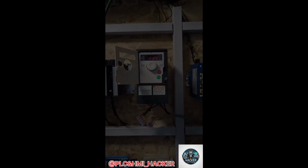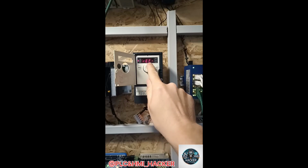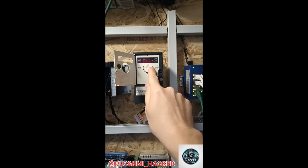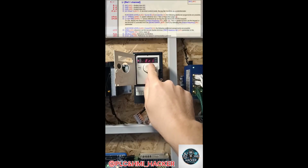We need to change where the drive should be controlled from. If we go to the CTL menu, we want to make sure the LAC parameter is set to 3. Then we want to set FR1 and 2 parameter to MDB. This will set the reference channels to Modbus mode.